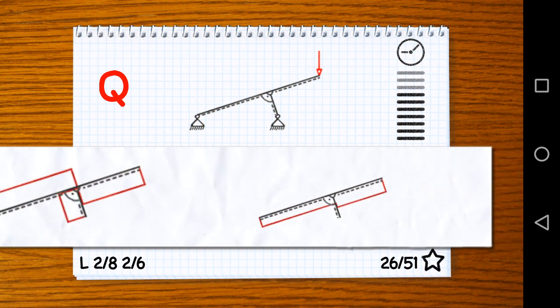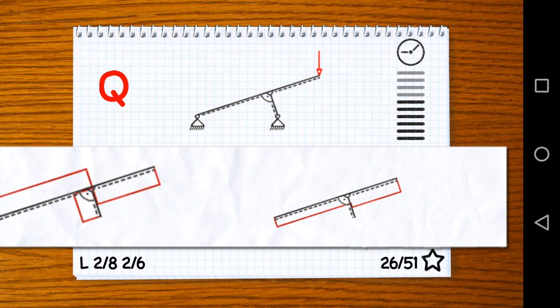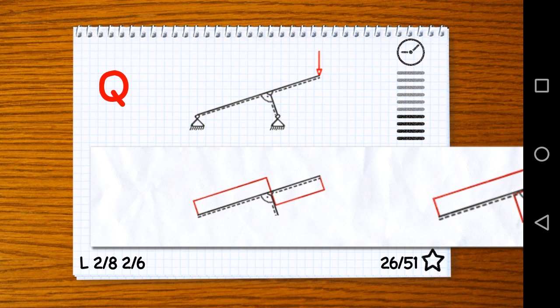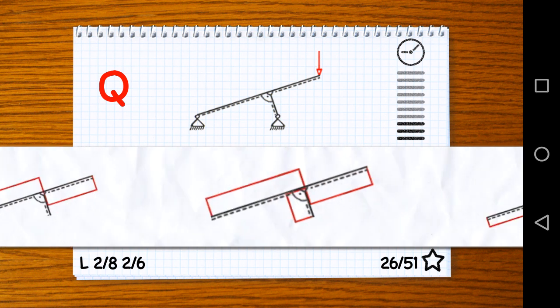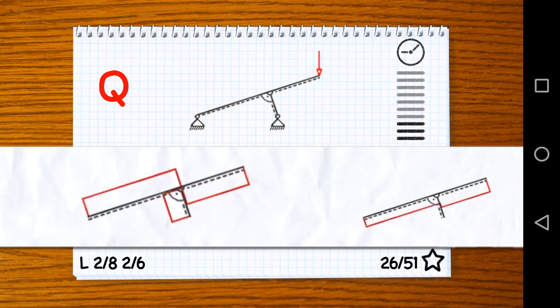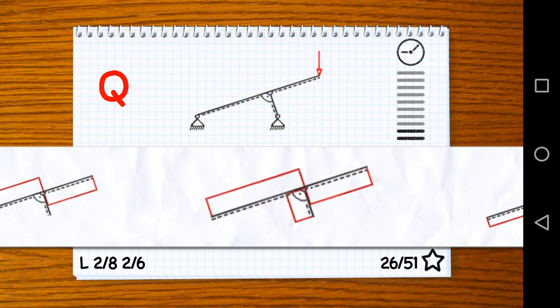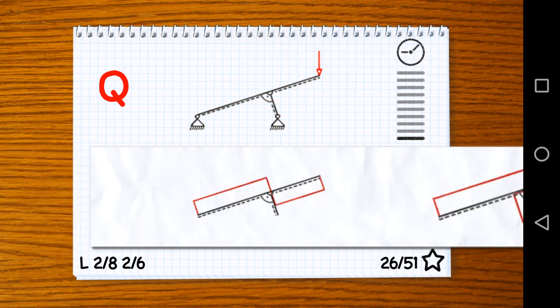From the right pin support up to the hinge, that's a rod. That rod can't have any shear forces except if it's loaded perpendicular to its axis, and that's not the case here, so we can't have any shear forces in there, so the middle answer here is wrong. And now the jump, the normal force in that rod is gonna bring us back to a negative value. So here's the answer.